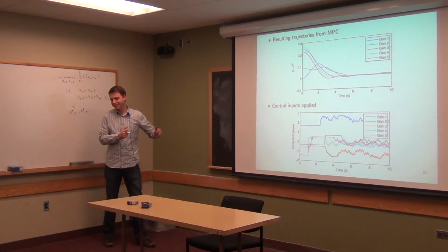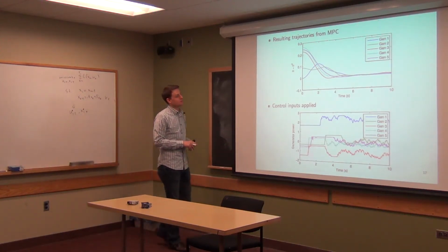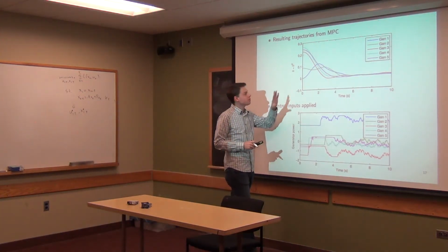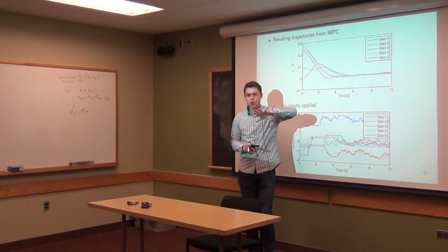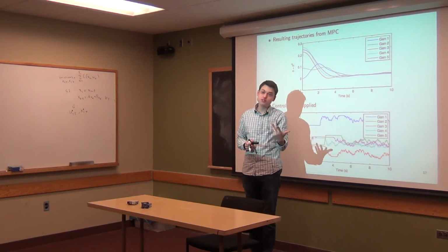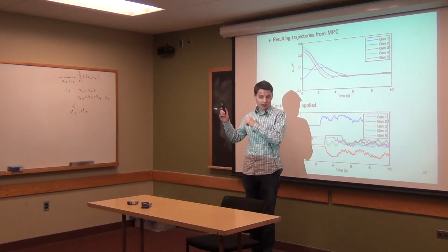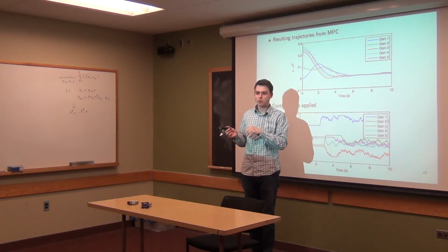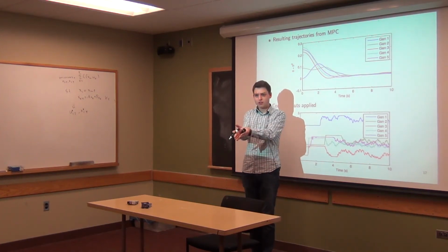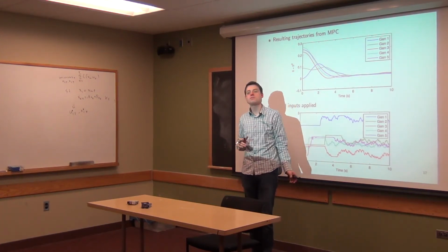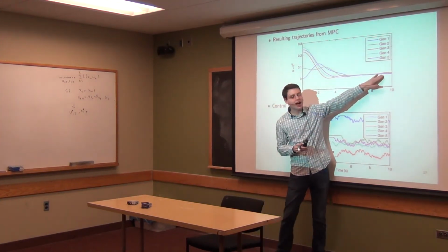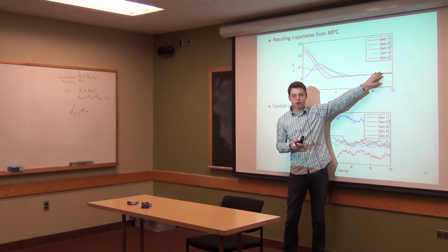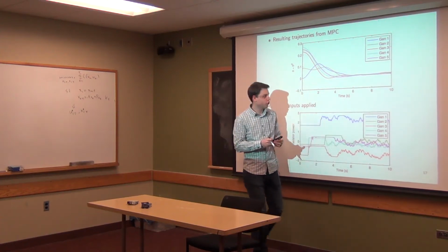Well, here's what happens. As with what we saw with LQR, you start up here. So this is now a stochastic system. There is noise that corresponds to varying loads. People are turning loads on and off that we don't know about, and we're trying to regulate the system around the nominal value given all that noise. And what happens is when you run MPC, it is in fact able to regulate it.